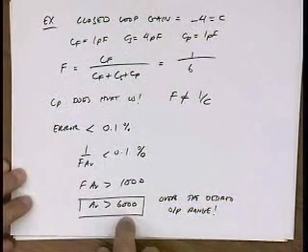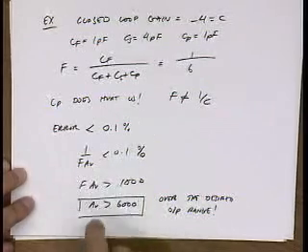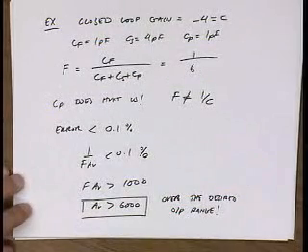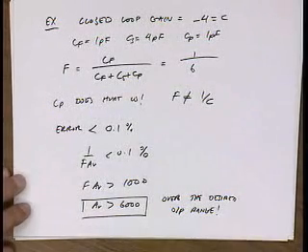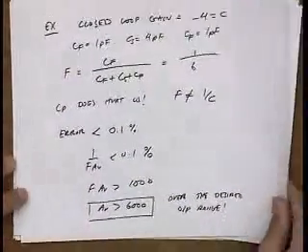So you might actually decide that you're going to eat up a lot of your error budget with just this gain error and make everything else fast, right? Because the other source of error is a dynamic error, which depends on the speed of your circuit. So that's an important trade-off.